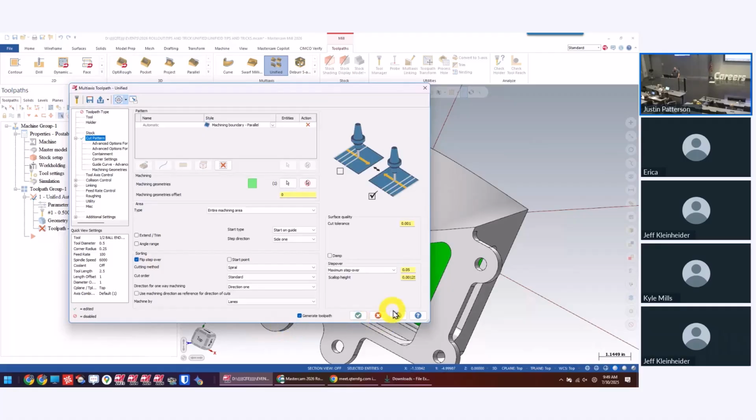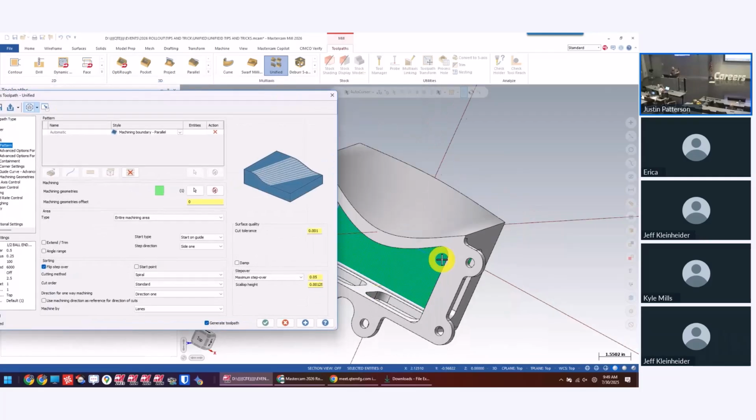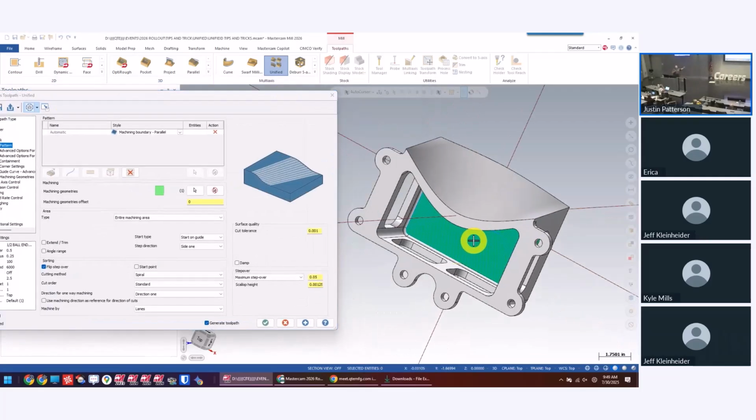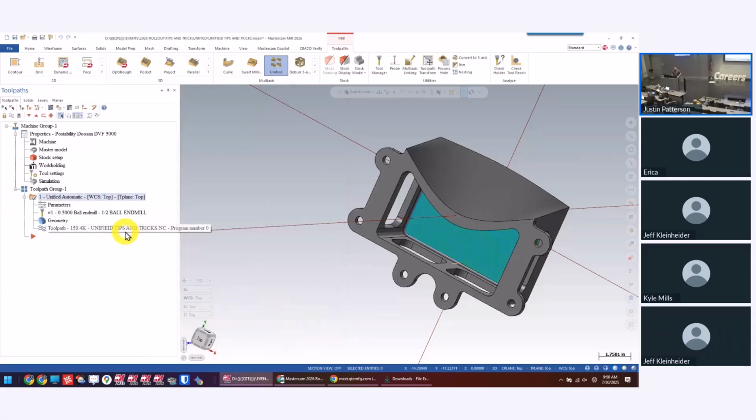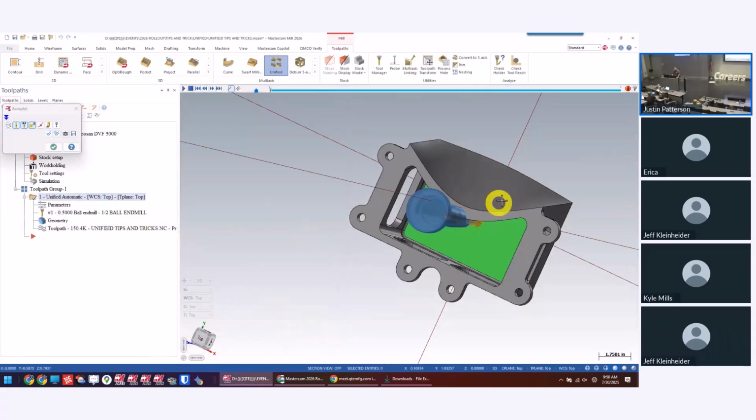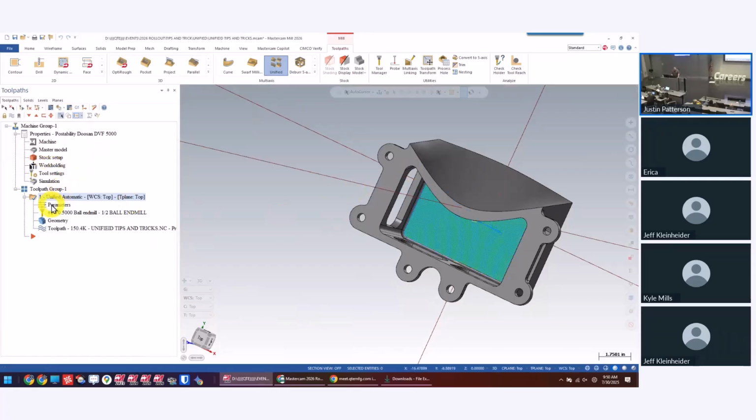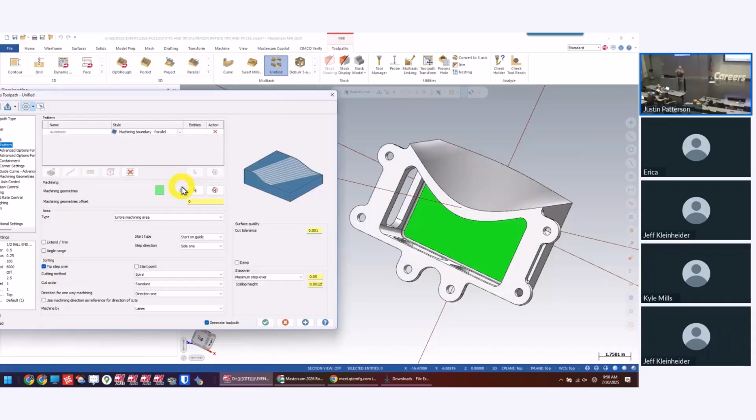Here's one product enhancement. Matt, you might write this down if you want to. The blue plus is amazing. If you guys don't know it, the blue plus automatically calculates our toolpath here. But I wish there was a quick back plot button I could hit instead of getting out of the toolpath. Like if there was a button here that I could hit to just do a quick little back plot, that would be amazing. Because right now, if I want to check it, I hit the green check and get out of the toolpath, and then I can run back plot. But see, now you see I'm starting in the center, working my way out. Okay, so 1 and 2, cutting what I want, how I want.